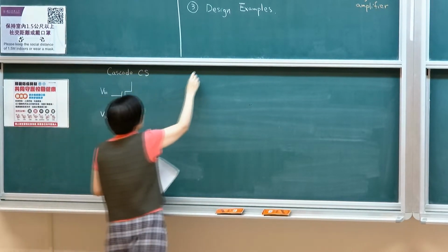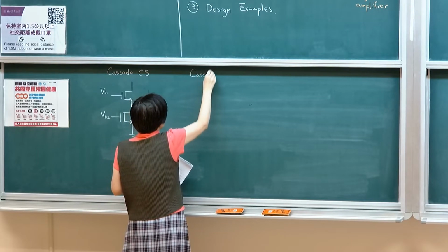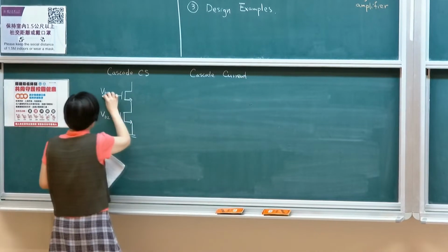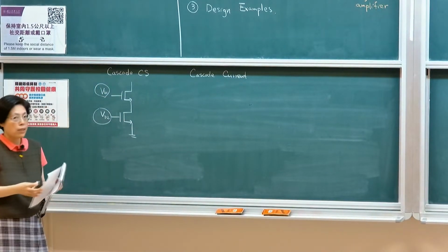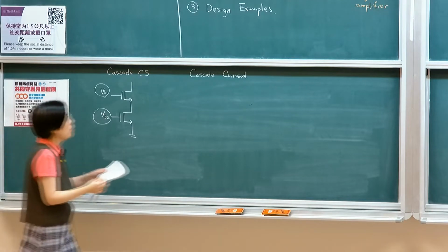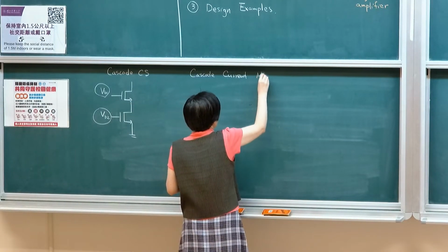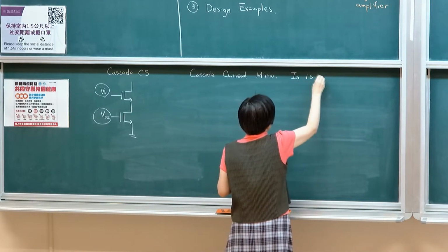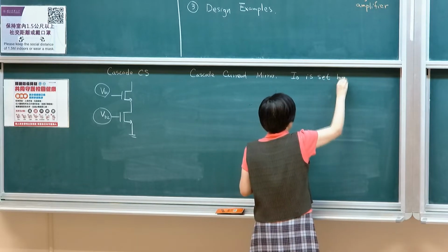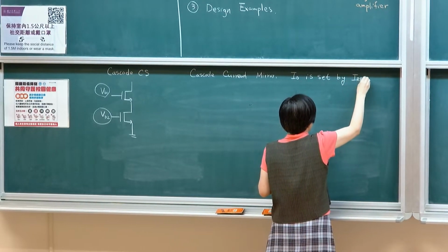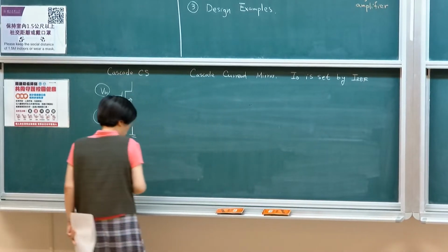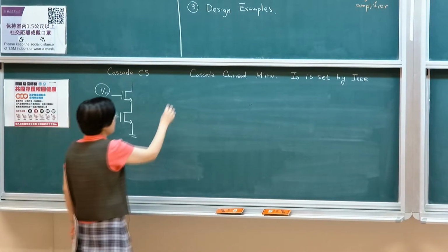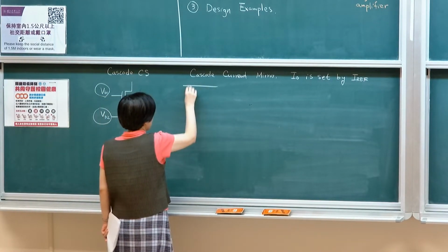current source. If you want to do a cascode current mirror, meaning that the current is being set not by a voltage but by a reference current, it's still a cascode structure, but its current is set by a reference current source. The basic structure is fairly simple. If you want to construct a cascode current mirror, it will look something like this.